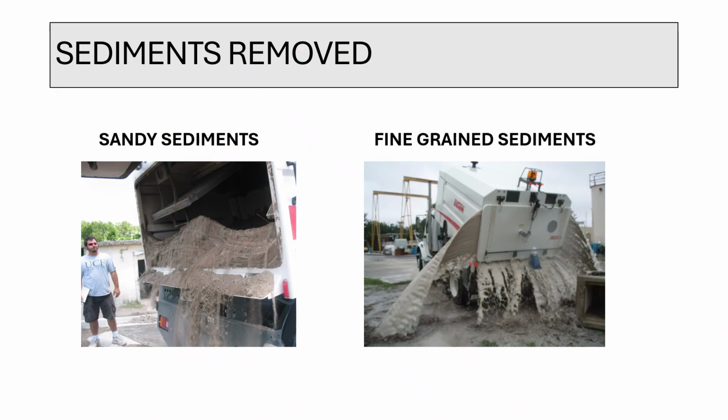Here we're examining the quantity of solids collected after a 1-hour cleaning session as part of permeable pavement maintenance. The data distinguishes between 2 types of sediments that were removed. One pavement had a clear visual loading of sand before cleaning, which resulted in a collection primarily of sandy sediments. The other pavement, however, showed a visual accumulation of various debris, including finer particles like silt, and consequently yielded a higher quantity of fine-grained sediments after maintenance.